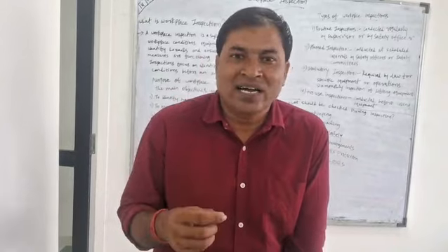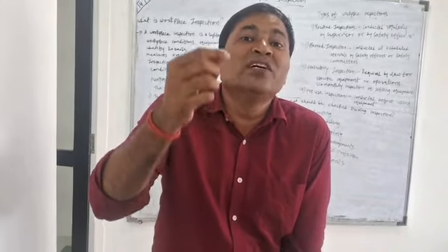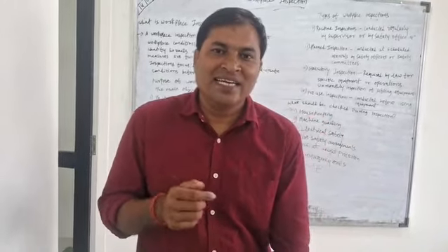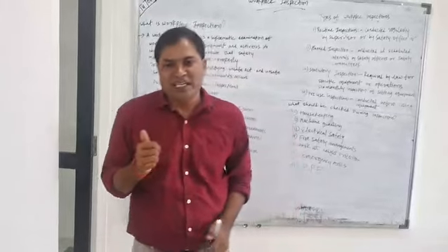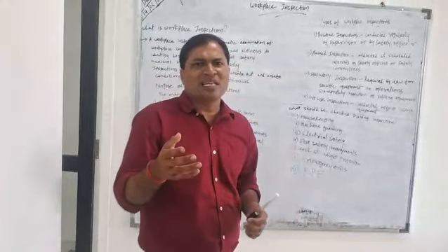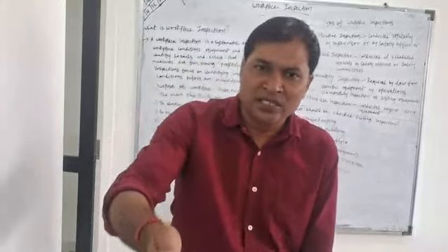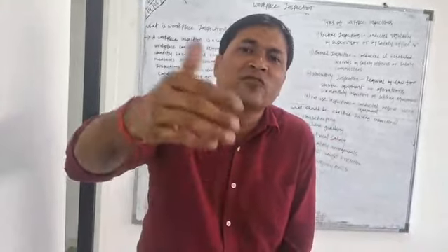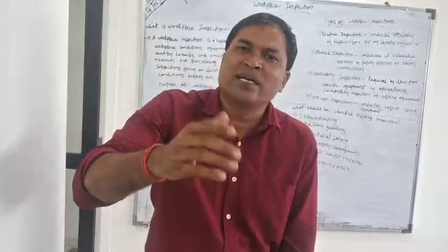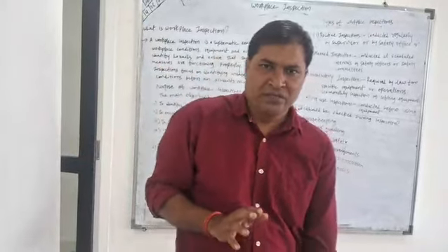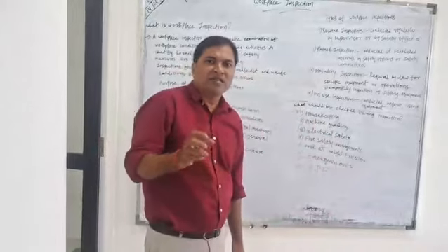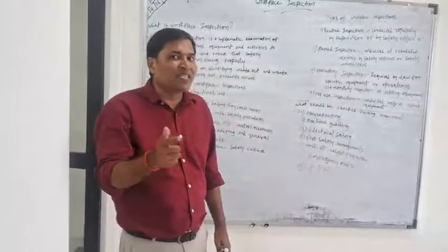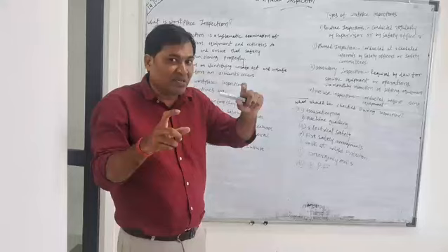So that requires planned, scheduled inspections. So that day you need to do the planned inspection. It may cover, like, after 3 months. After 3 months you can go for the planned inspection, or you can go for 6 months as well. It depends upon your company policy. Okay, that requires planned inspection. That is the main difference between routine inspection and planned inspection.